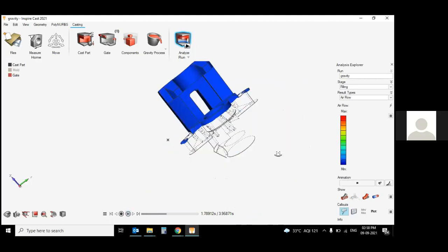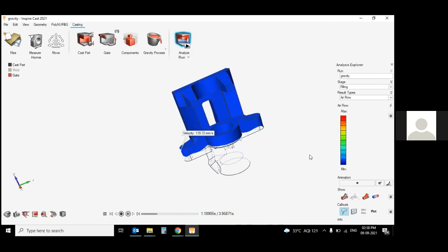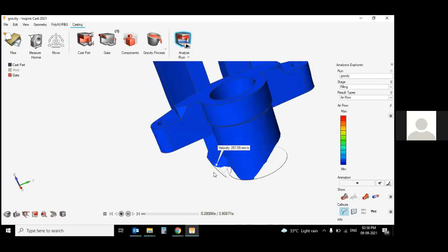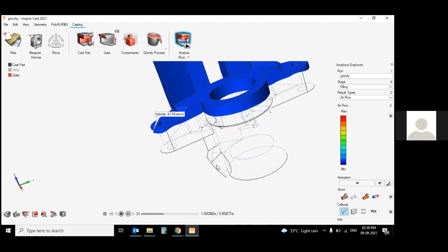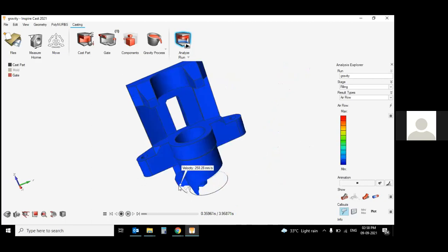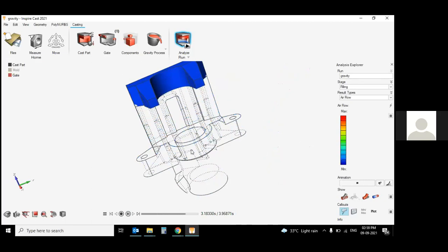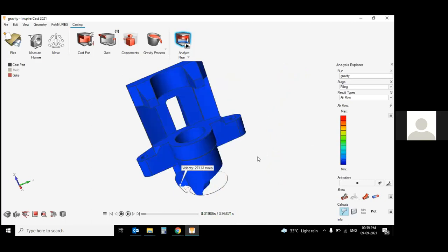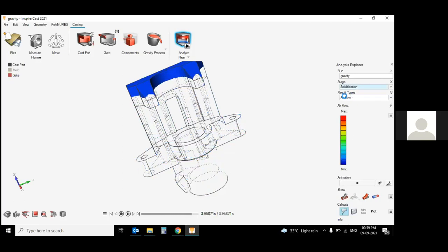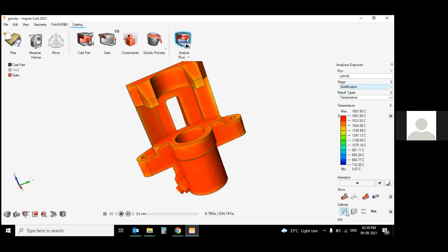So this is my feasibility check test, in which we check the feasibility of the component. Suppose you are not getting the result from this particular gate point, then you can modify this gate point. You can feed this component from below, from the top, and from the back, just to get the results and move towards the solidification. In this solidification, you can also get the call outs.